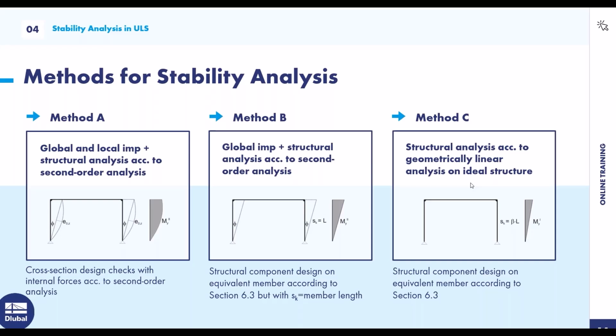For the design of the lateral torsional buckling, the application of the second order analysis is also required with that method. If you want to do the lateral torsional buckling design for the horizontal beam, then you also need to calculate according to second order analysis for this method. We show this method also because we know in the studium you have to define the real buckling lengths.